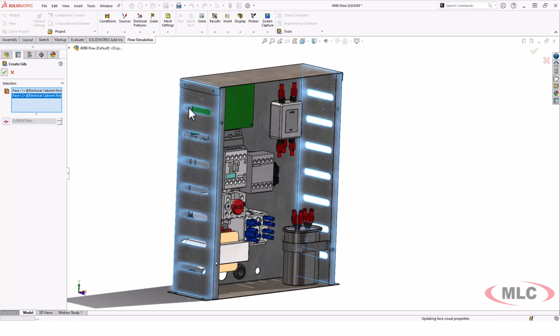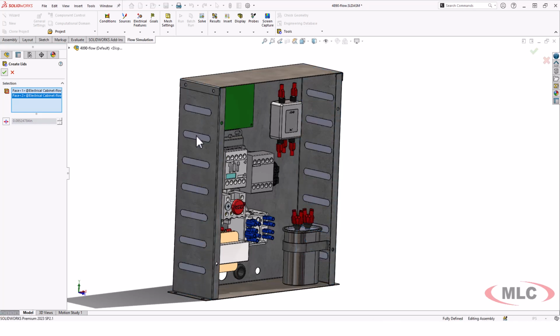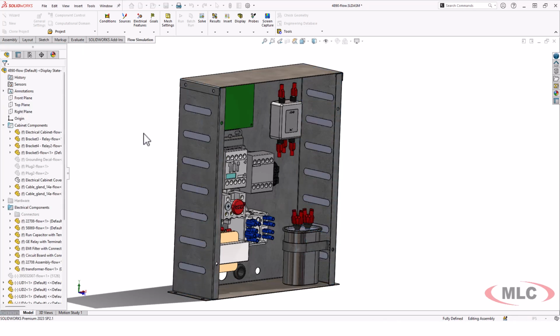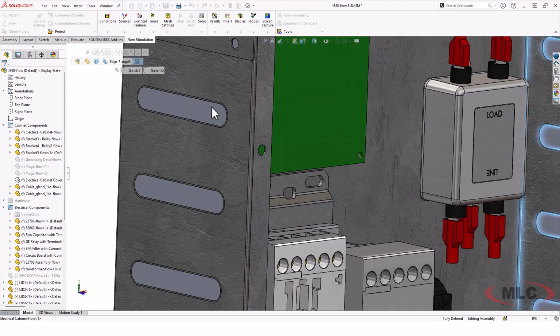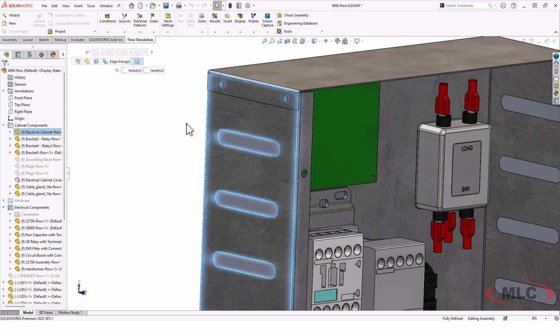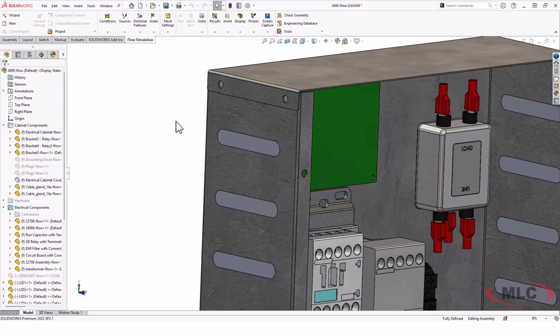Now, because it's creating one lid per opening, what I'm going to be able to do is come in here and select boundary conditions and measure flow through each of these lids individually. A lot of times I'll actually create dummy bodies like these lids interior to something. Like, for example, in between two valves in a channel, in a system, in between those two valves I want another pressure drop in the intermediate area. Create a lid there, exclude it, and then you have now somewhere to define a condition or to measure something.